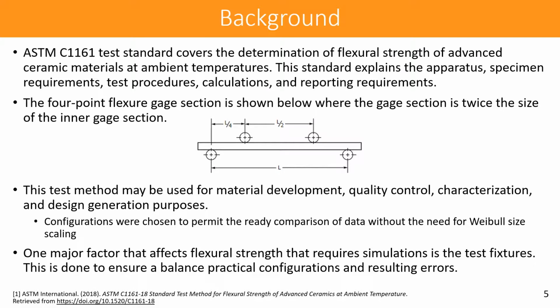Next I'll talk a little bit about the background information that leads us to our objectives. We'll be characterizing the material properties of these hermetic seals. By doing so, we'll follow the ASTM standard C1161, which covers the determination of flexural strength.